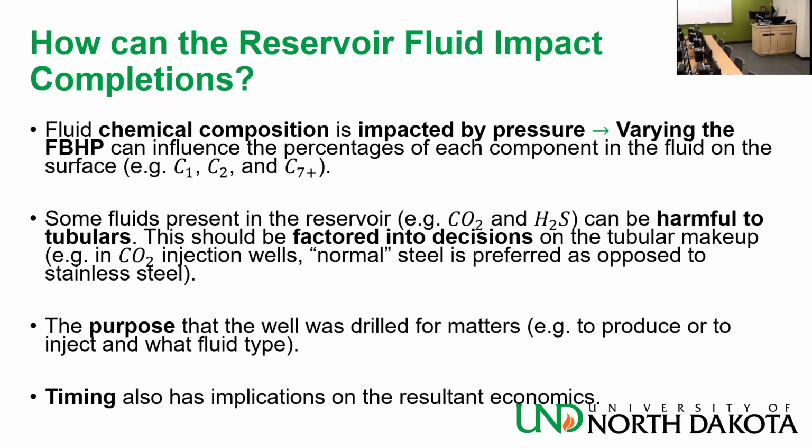Vaseline, for instance, which is a petroleum fluid, has 64,000 centipoise viscosity. And then water has 1. We used to do hydraulic fracturing experiments in the lab, and we wanted a very, very viscous fluid for scaling purposes. We chose Vaseline, but we couldn't put Vaseline in our tubulars to inject. We had to warm it up. And when you warm it up, it starts moving, but as soon as you stop heating it up, it slows down. And then it's very hard to clean your palm and everything with it.